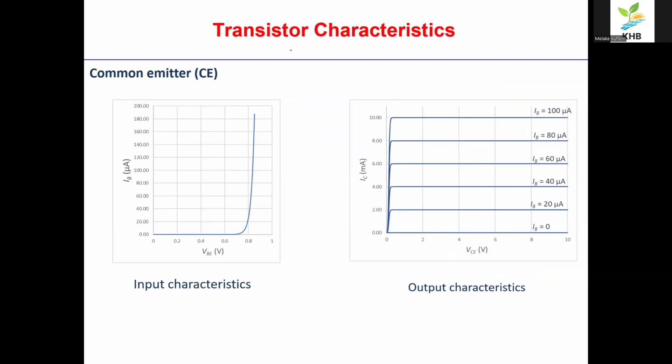Now if we look at the characteristics of the transistor, we normally have a forward bias at the base-emitter, and then this is the collector, and this is the bias VBB. So what we're saying is the transistor will conduct in forward bias when IB draws a lot of bias current. This is the base current when the forward voltage is around 0.6.